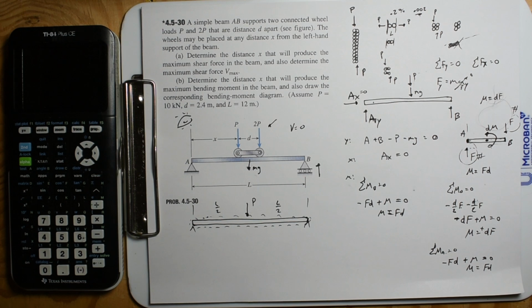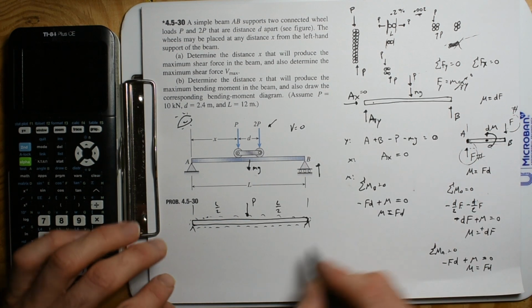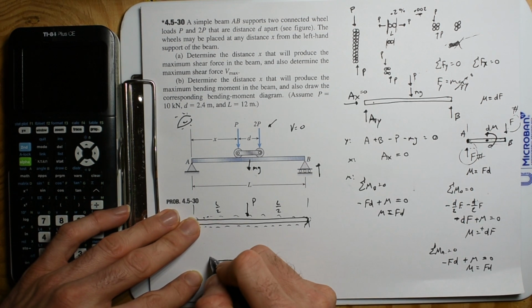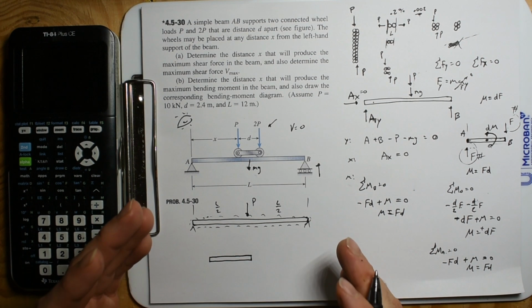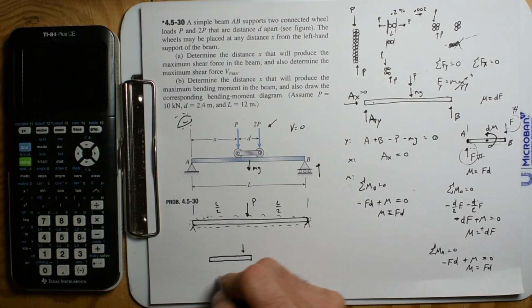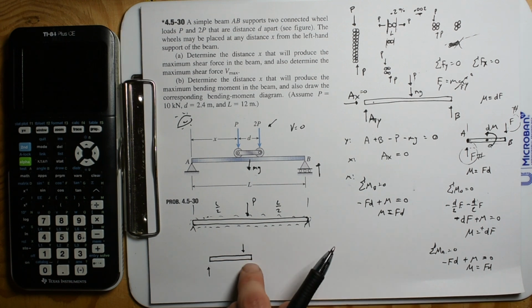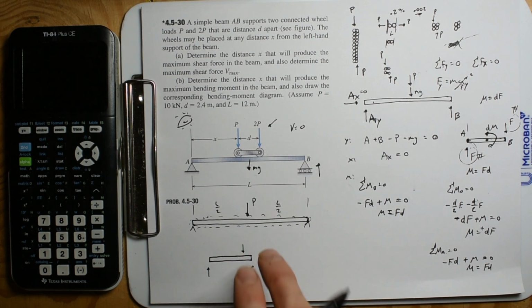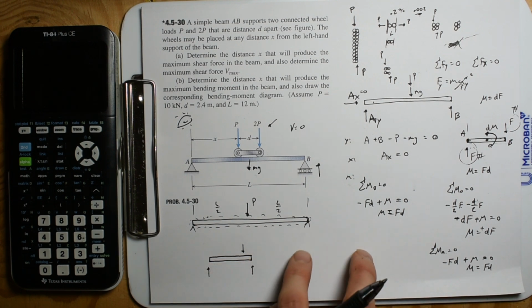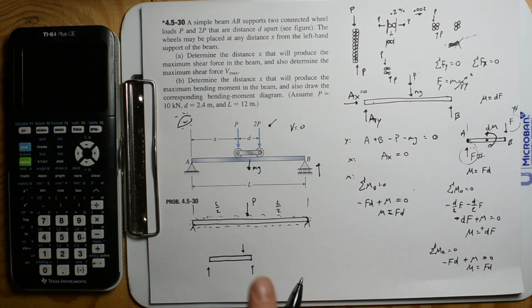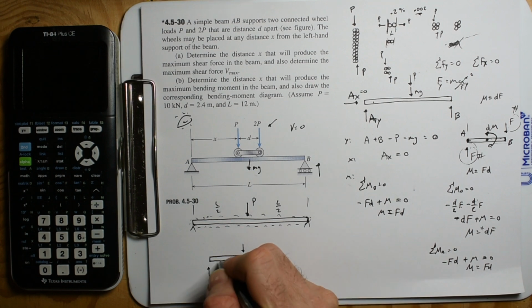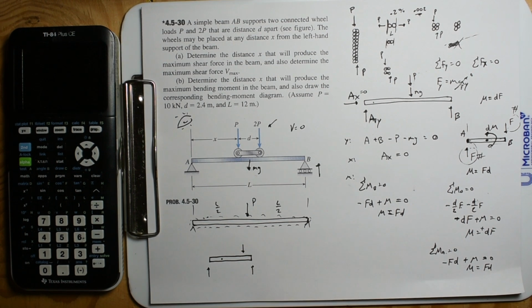And let's slow this one down because I think I have a cool way to explain this. So again, we're going to take this little chunk of beam and then pin it to outer space, and then we start to apply a bunch of different forces. Let's say we got that going on, and we know from observation down on Earth that it's not moving. So the fact that we put this in outer space and apply all the same forces, it's also not moving in outer space. So that means that one, it's just not moving, but two, you can pin this thing at any point you want to.